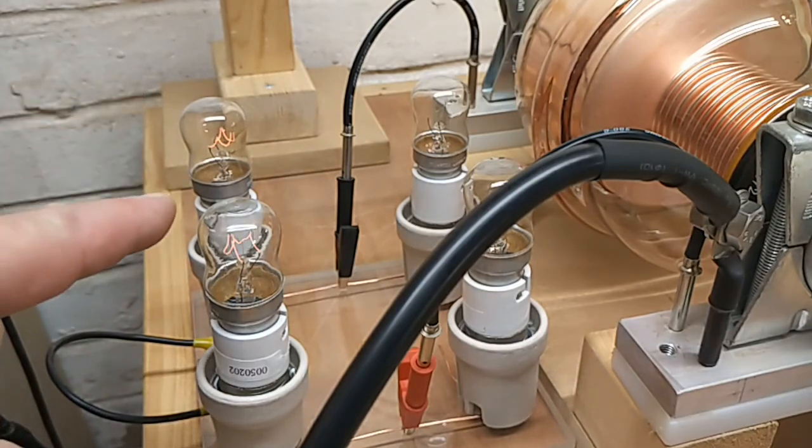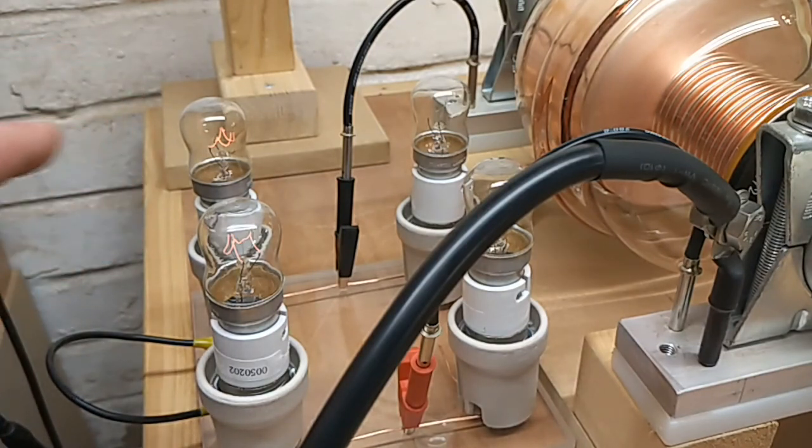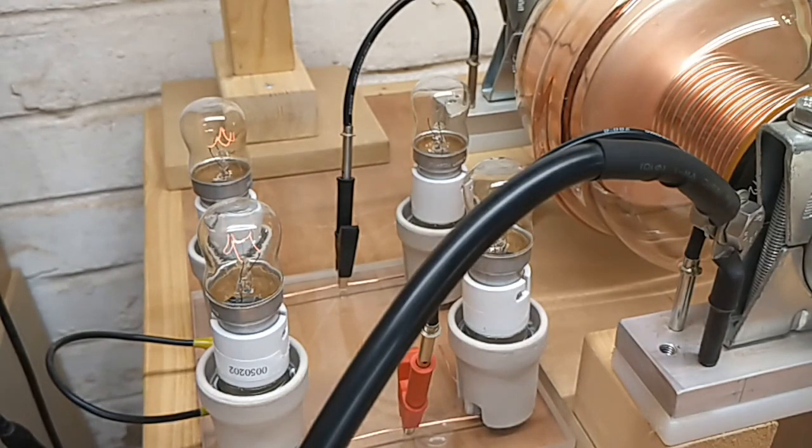Now what I'm going to do is change the tuning capacitor in the transmitter over its full range, and we see what happens there. So that is capacitor fully wound open, and really no power transferred, or very, very little. We can't discern it in the bulb. Gradually winding the capacitor in, there we are.